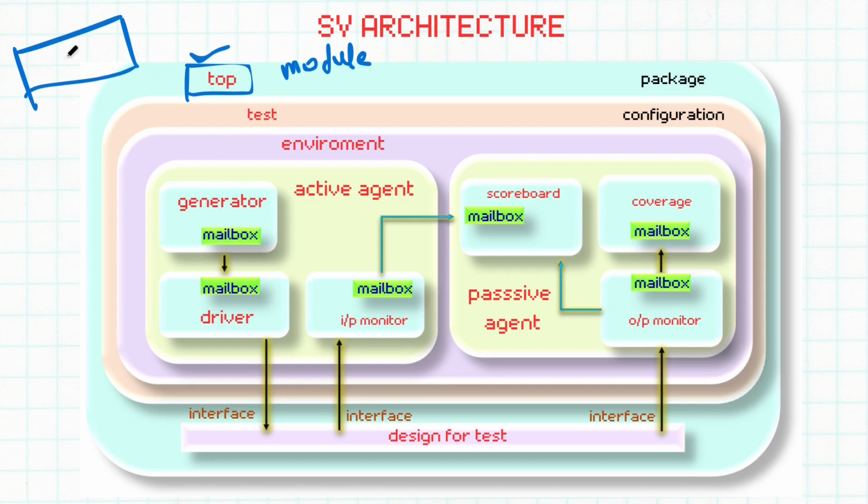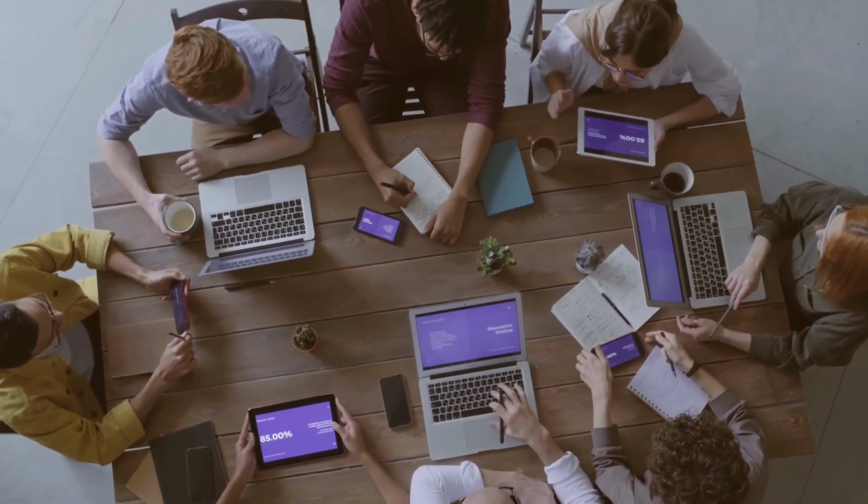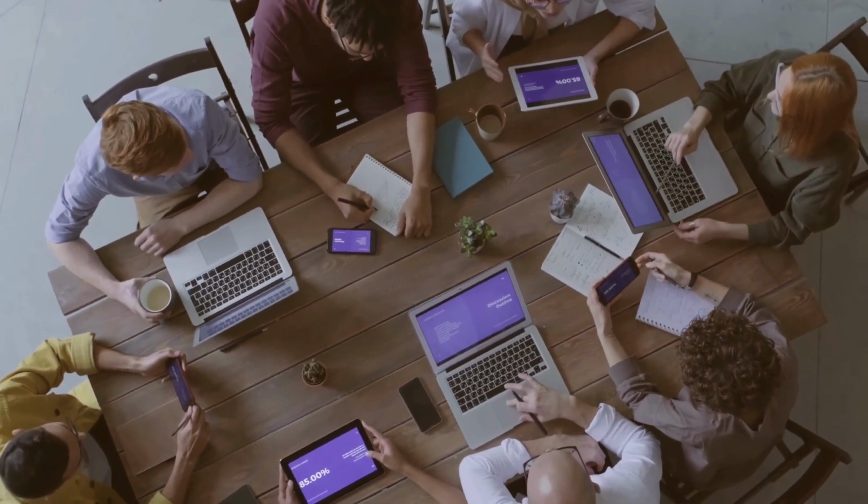Now after deciding how many test cases we have to write, we go towards our test bench components, because for testing these features and writing test cases we need a test bench. For that we assign the job of writing one block of the test bench to each person, like the monitor and scoreboard, and someone will write assertions, someone will write checkers. For example, if you have 10 engineers for designing and verifying a chip, then there will be 6 engineers for verification and 4 engineers for design.